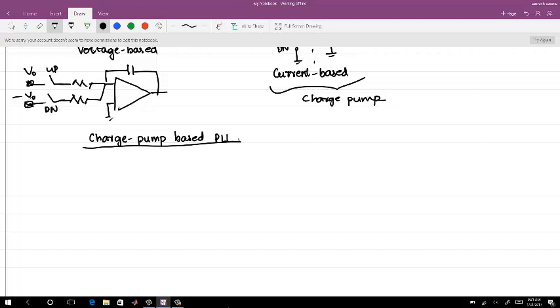So think about it. In all the analysis we are going to do, we are saying that the loop has settled, meaning the PLL is locked, and all the analysis with any frequency transformation, Laplace or Fourier transformation, is in a steady state. If there is any small disturbance in the system, how does the loop react? For that small disturbance, we try to find the gain of each of these blocks in a linear region, which is small output versus small input.